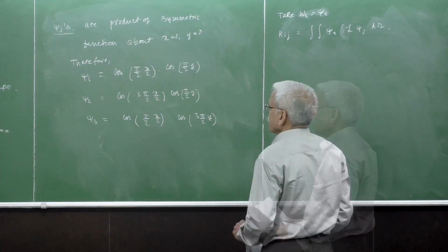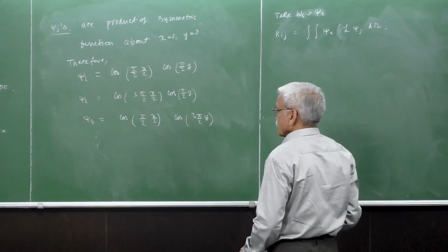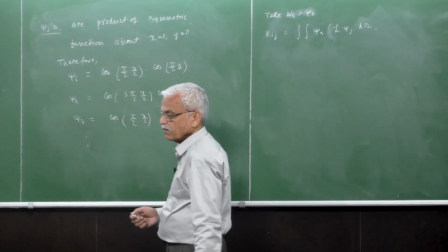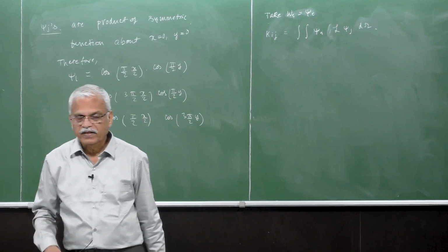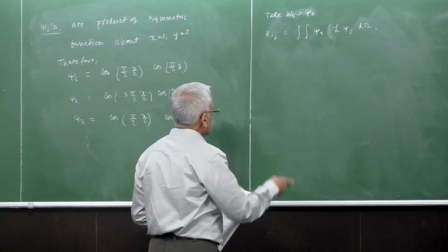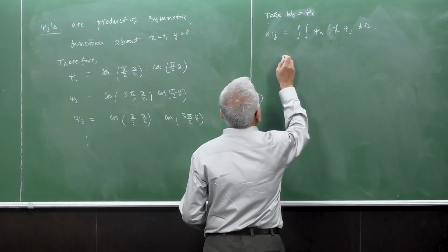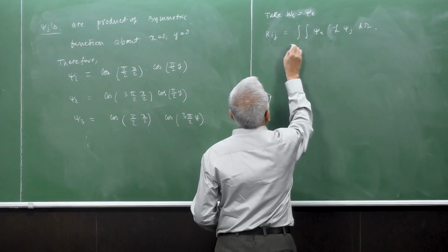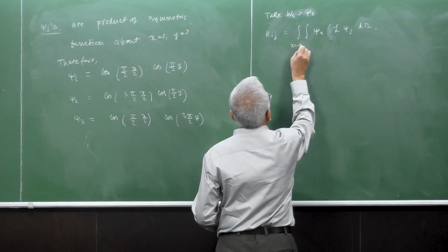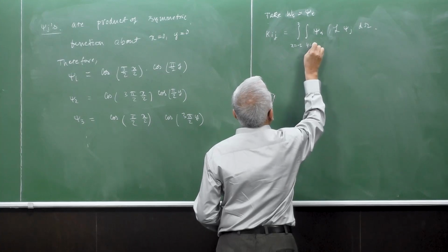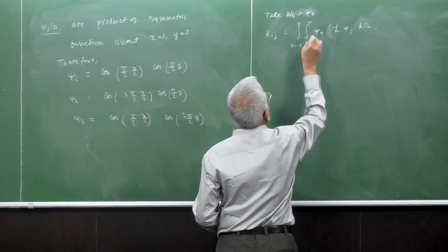And then we can calculate all those algebraic equations, which are in the form of the matrix K multiplied by vector A is equal to vector B. Kij is the one where the integrals have x going from -2 to +2, and y going from -1 to +1.